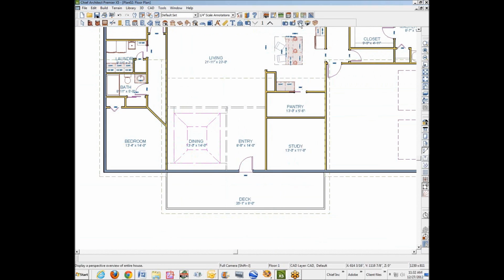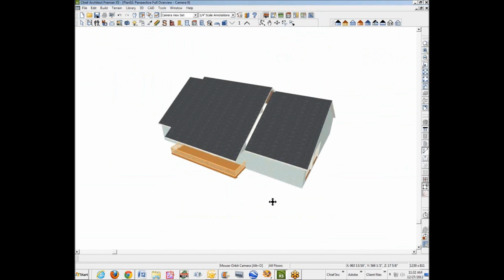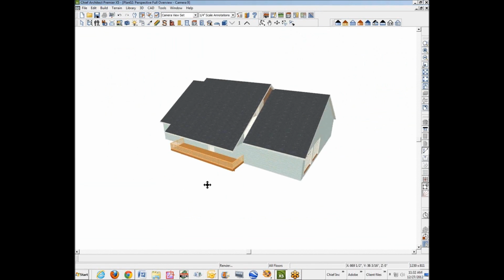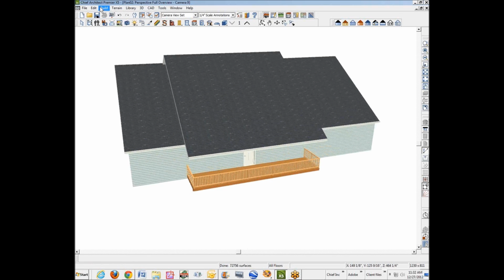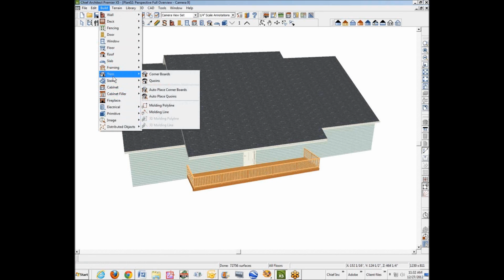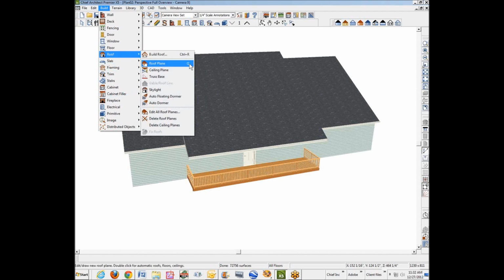Let's see what the overview of the outside of this looks like. Okay. Well, you know what? The dormer tool probably wouldn't work very good here. Probably what you did. And your plan doesn't show that this dormer is anything other than decorative. I suppose it might be a skylight or something, but you didn't state that. Let's just see what happens here. But I would not use the dormer tool for this, per se. I consider it a waste of time. Well, we'll give it a shot.